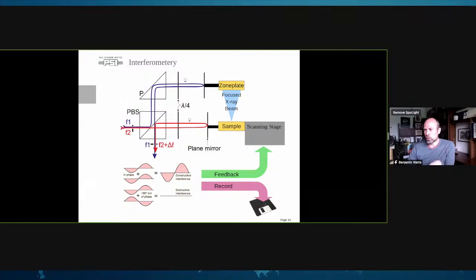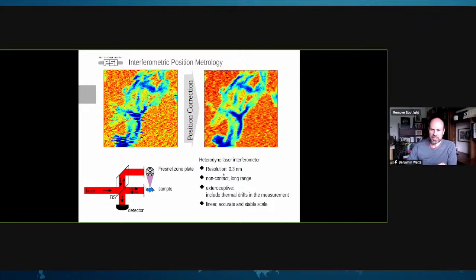And we can also record those positions to use later. So if we don't get the position we asked for, we at least know the position that we got. And so we can use that to fix glitches in our scanning. So on the left here, we have an image where we had some lines where, as we're scanning across X, the start position was off by a bit. And so we can see that line of pixels is just shifted. So because we measured the positions for each pixel, we can use those to reinterpolate the image and remove those